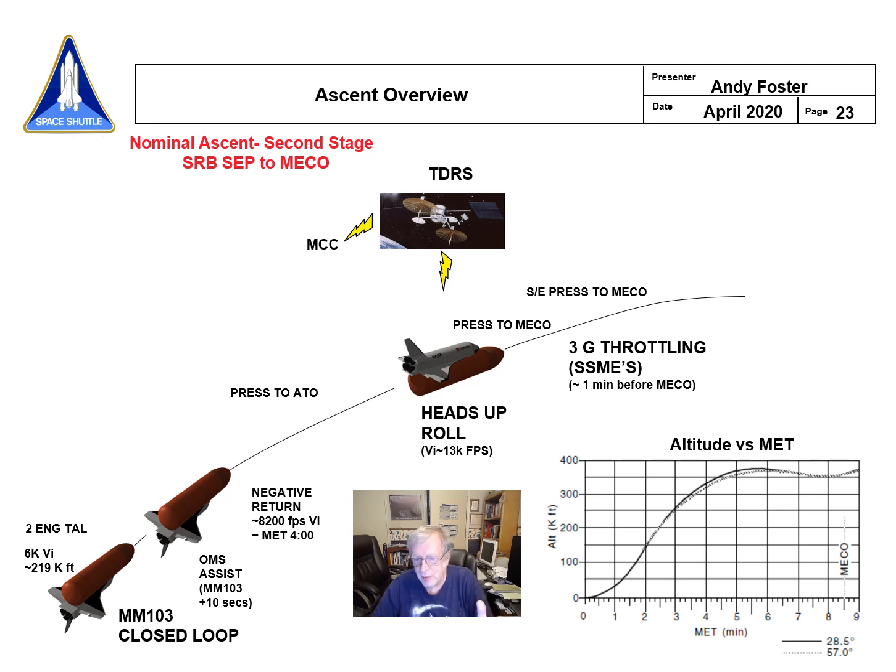And if you're wondering what the trajectory looked like, this is showing you over here, and it shows you for 2 different inclinations. And this is altitude versus mission elapsed time with the MECO right out here. So you can see we kind of did this curve up and then hump over, and then actually a small dive. And this is to get us what we call the right flight path angle at MECO. Our main engine cutoff is MECO, and that flight path angle helped determine, along with the velocity, what the orbit was going to look like.